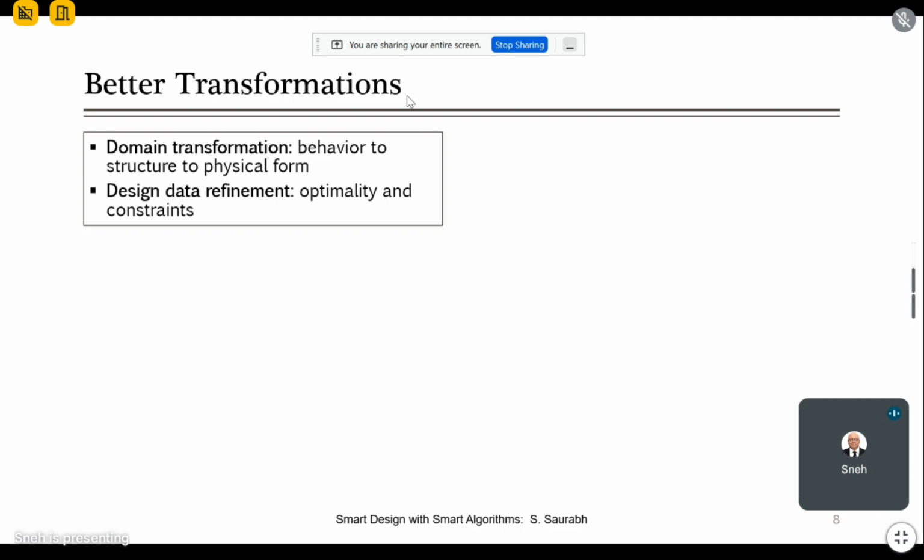But when you have a netlist, you have a cell instantiated for that, and you have more information, your data has been refined with the transistor size. And then later on, when you make the layout, you make the connections and interconnects. Now your data is further refined, right? So as the design goes from the top of the flow to the bottom, data goes on refining, and the domain is being transformed, and so on, right?